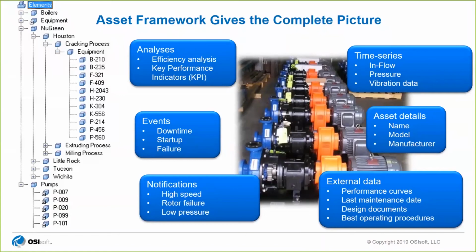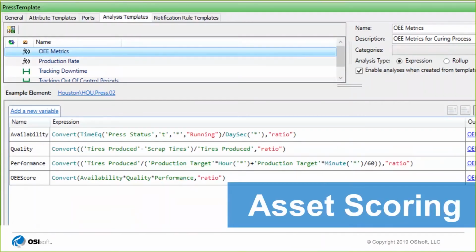They could be high-speed notifications, critical events that you need to know just in time. If your pump amperage is ramping up, you want to know when it goes above a certain critical level, or if the pressure is bottoming out, anything like that. You can receive a text message or an email,